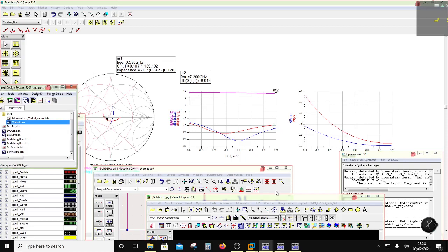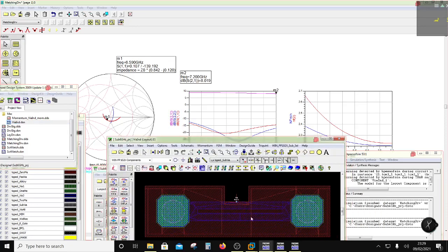So this is a small exercise in small signal matching. Large signal matching is going to be a way different because there the idea is not the noise figure, rather the idea is the compression. So I would show you that you do not have to rely on load pull. You can do this if you know the impedances. So in the next session, probably I will show you how to do a large signal tune. So in this exercise, we have seen whatever we could do with a small signal tune. So I'm going to stop here.